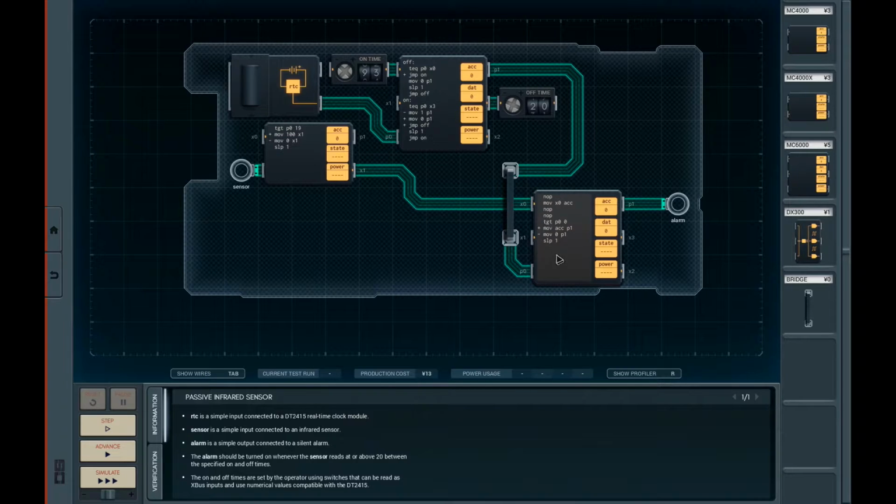So how do we handle that over here? Well, with this X bus thing, you have to read and write at basically the same time. The data gets put on the bus, and then you can't do anything else until you take it off the bus. And if you read it too early, you're not going to get anything. So I've put in a no operation command here, and then I'm moving the contents of that bus to the accumulator. And then I've got a couple of other no-ops here to wait for this thing up here to finish its processing before we then check P0 and see what's on there.